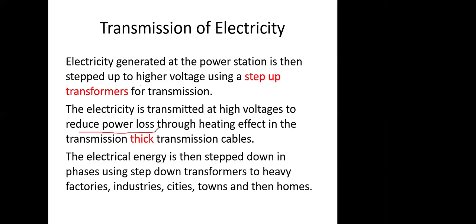So the reason why we have step-up transformers is to step up our small voltage at the power station to a high voltage for transmission. That high voltage is because we need low power losses as we transmit, and to reduce power losses even more, the cables used in transmission are made thick such that the resistance in them is small.